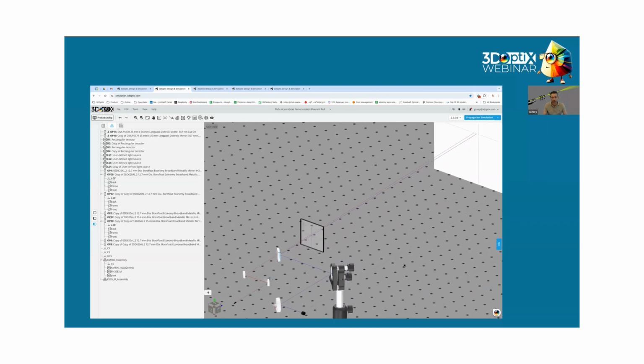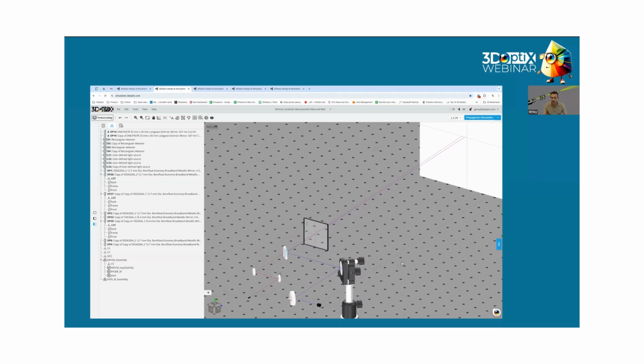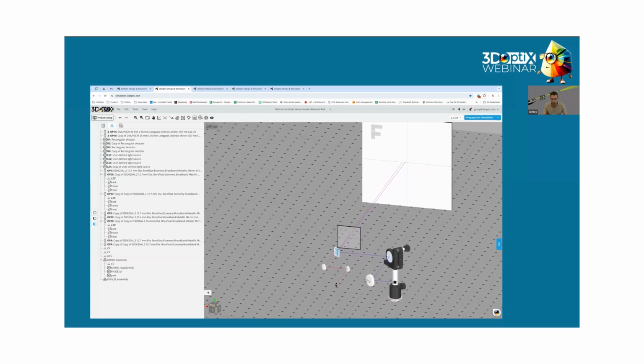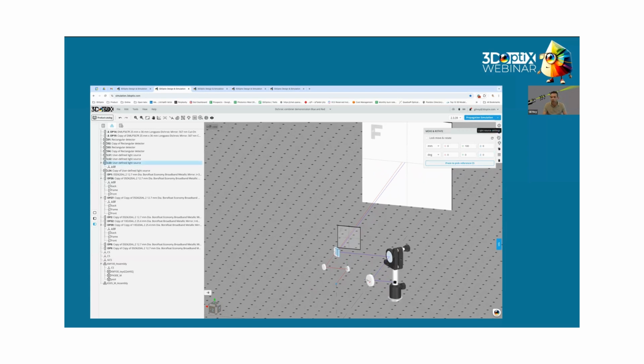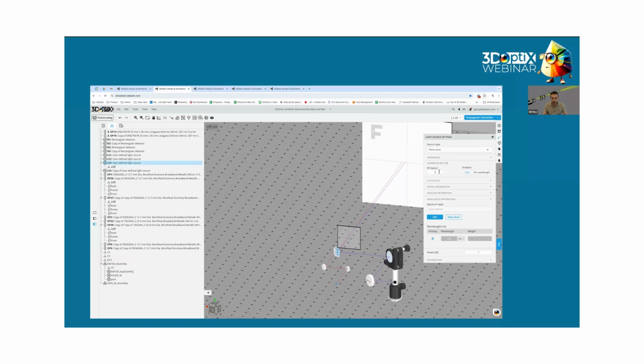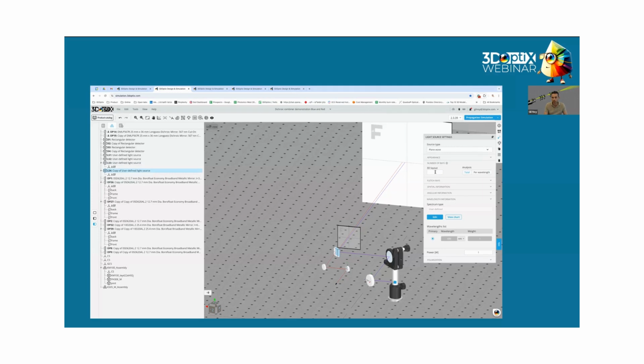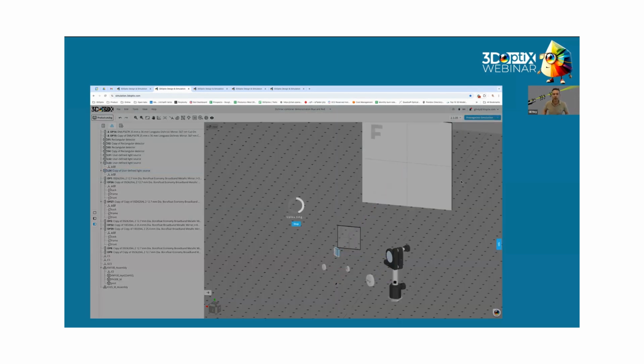Here I applied a kinematic mount with 2 knobs. Maybe this is too much. So this is very important. And just to show you to complete, so I would go and change here the source to 30. And I would change here this source 30 as well. And now when I propagate, we'll get the full size of the rays, of the beam.